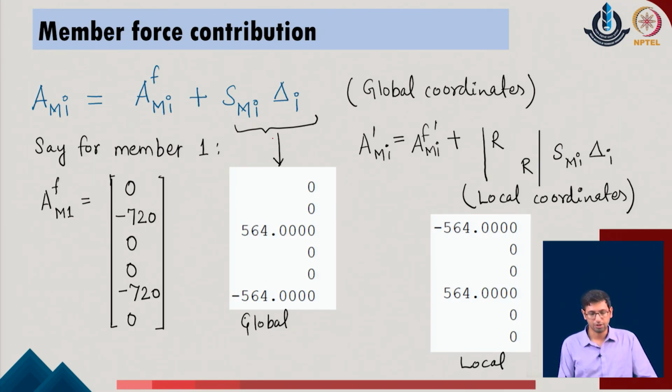As you calculate this value, it gives you the standard expression like this. We add along with that the expressions with respect to the given system. The way we have defined it here, this value gives us the member force with respect to the fixed end part only, and these are the evaluated values. Once we convert all these values, we evaluate them as global values. So these are the values which appear. When we convert them into the local coordinates, these are the corresponding values for member 1.